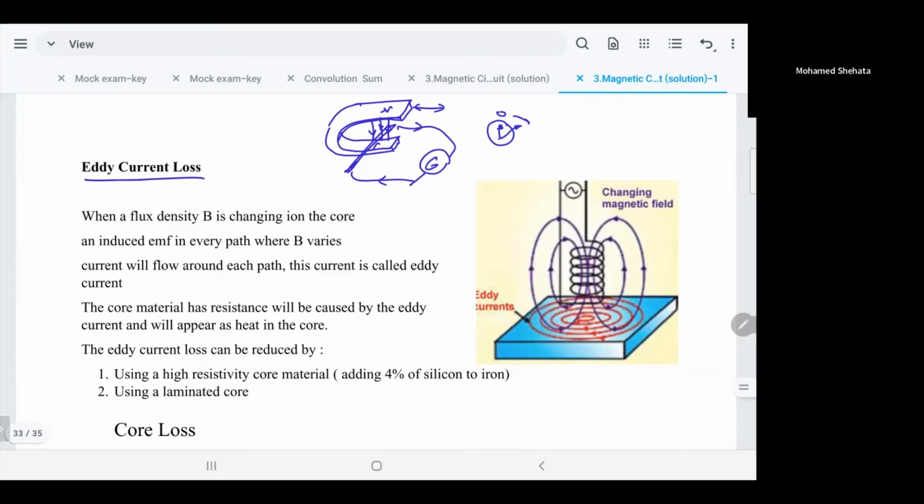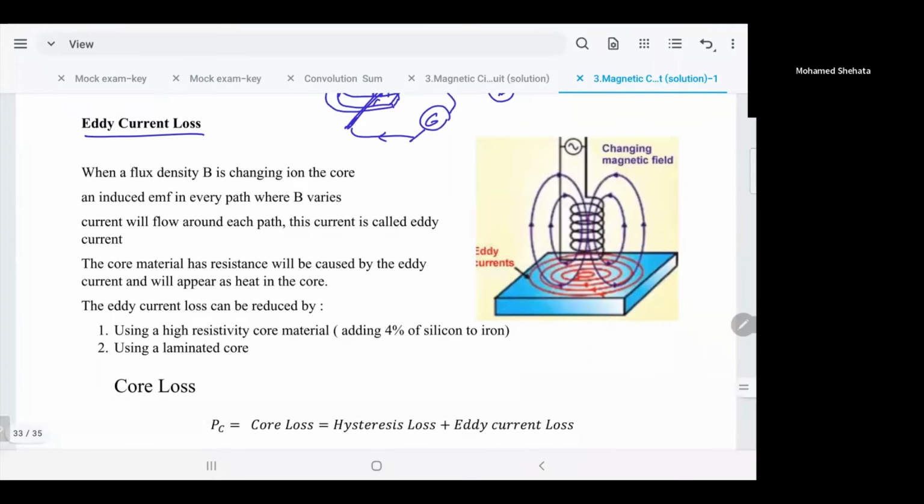And that's why I observed that if you have an adapter or charger that has a transformer, the one that we have now doesn't have a transformer, but if you have any equipment or device that has a transformer and you plug it in the wall and you don't use it, it gets hot. Because of the magnetic field, you have the eddy current and then you get the loss. So it produces heat, that means there is a loss because of eddy current.